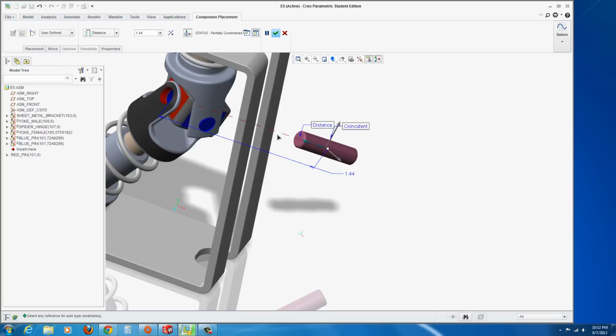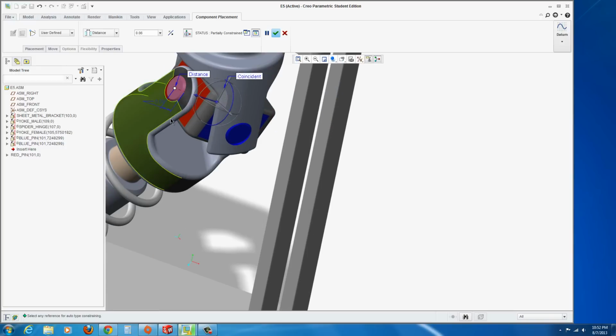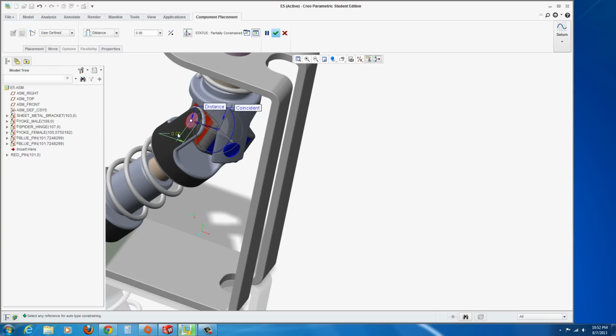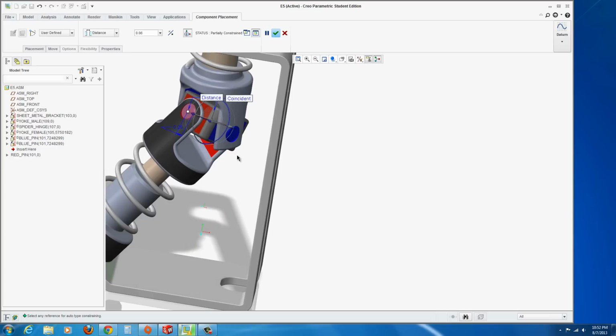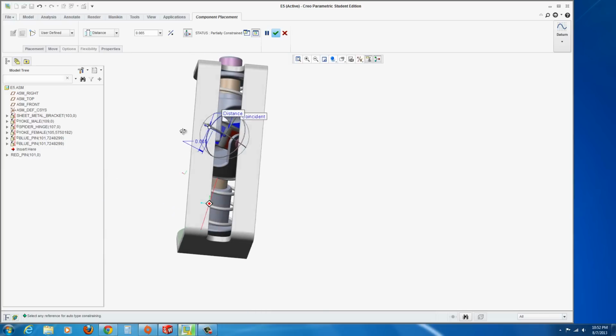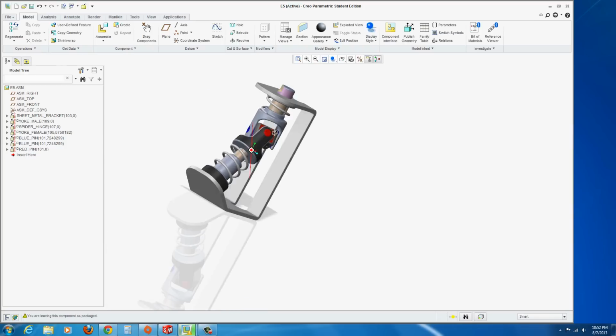And let's grab the dot there and drag it in. Again, it should default to 0.06. If it doesn't, you can type it in manually. I believe 0.065 brings it in a little better, so it's nearly equal on both sides. Go ahead and hit the green check mark.